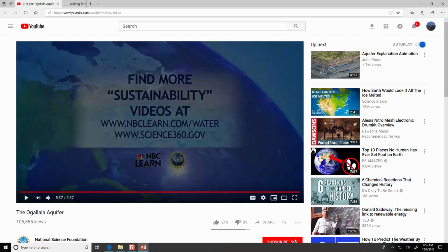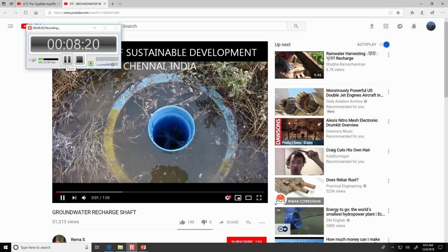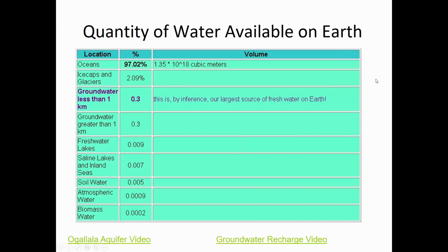Let's look at this groundwater recharge video. So the infiltration rate is improved in the well casing because, number one, the hydrostatic pressure is higher because the depth of the water is larger as it goes into that well casing. And then the other factor is that there isn't the risk of dust settling and closing off the pores of the soil.